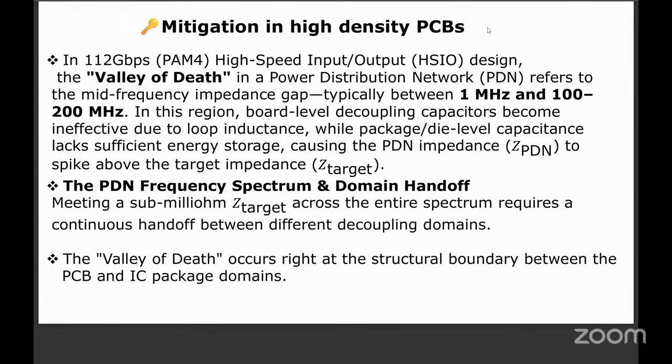First of all, your on-the-die capacitance will take from the package capacitance, from a mid-frequency capacitance, from low-frequency capacitance, and low-frequency capacitance from the voltage regulator module, and that has to be constantly getting replenished. So what happens? The mid-frequency is the one that has to not only give to high frequency, in the meanwhile, it has to collect from the low frequency also.